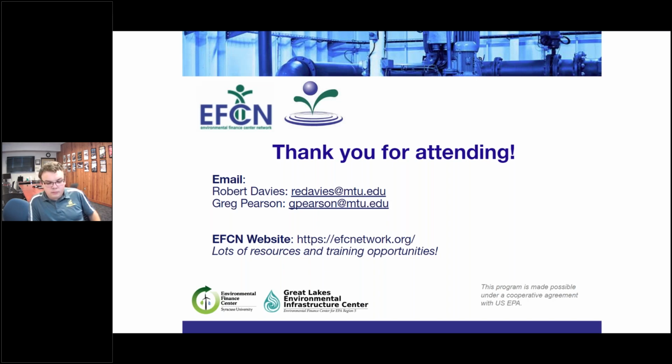We had a great comment come in that just says, I have heard of some operators who actively grow algae or duckweed in their lagoon and then use a pump and screen to remove the algae and thus remove some of the nutrients. Have you heard that too? I have heard that, especially with duckweed, and it's fine to have a bit of it in. It does provide a natural reaction. The duckweed provides some natural shading so you don't get as much algae, but you have to know what your lagoon's going to handle, and if it gets out of hand, it's going to completely throw the ecosystem out of balance.